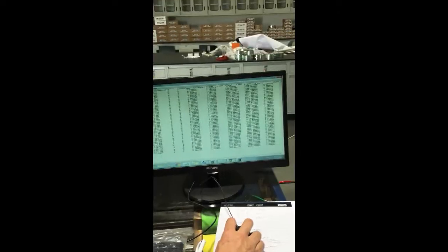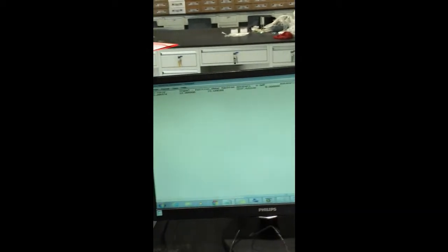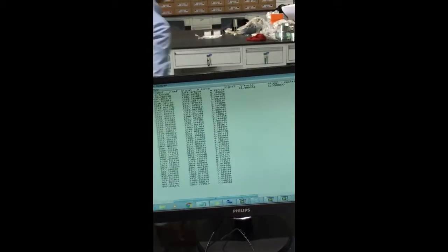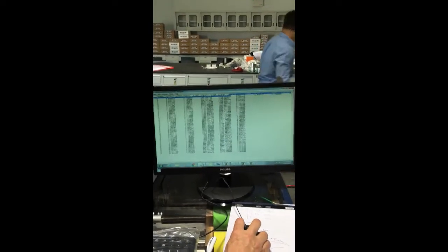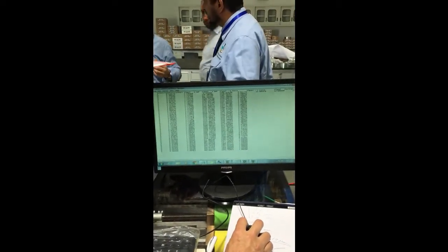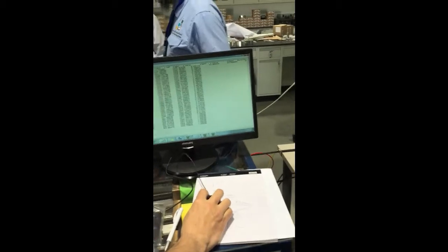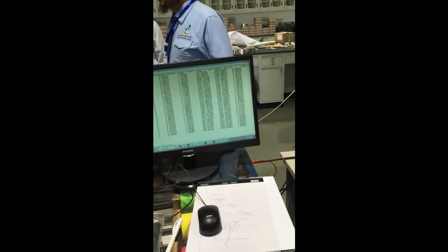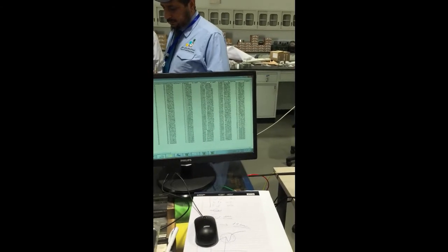And now here, and you see here. Horizontal force, vertical deformation, and you have 1, 2, 3, the three readings. When you move to Excel, it puts it properly, every column with its value. The date, the time, when the test started, when it finished, everything is stored.